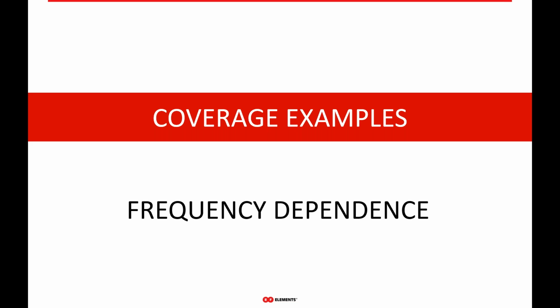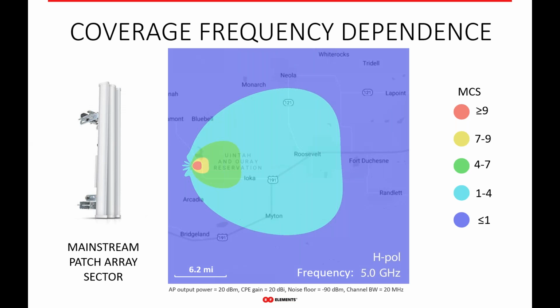So it's very important information for a WISP, since you use a very wide chunk of spectrum. Therefore, the antenna performance, in this case of coverage, should be ideally stable over the entire bandwidth. It's really important that you have very stable patterns as the frequency changes. So the frequency dependency of these antennas is something that you really should consider when you're purchasing an antenna.